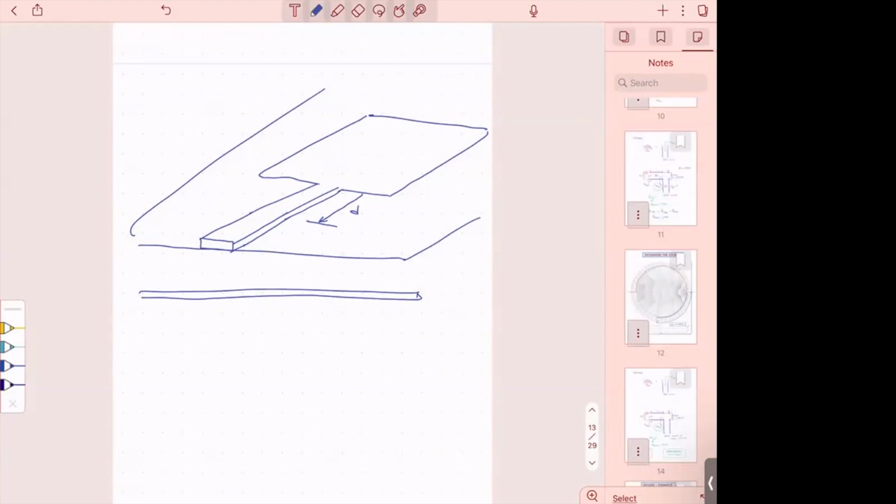So now I found a small distance for that. I found 0.1 something, right? Remember? Now I need to add a stub. The stub is going to be in series, even if, you know, for microstrip it's difficult to do a series stub. It needs to be in parallel. But in any case, what I wanted to tell you, even if it's not, let's assume you wanted to add a stub. Here, the stub that I'm going to add is going to be parallel because it has the same ground. All right, the transmission line.